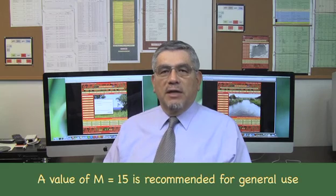In which T sub r is the time of rise of the inflow hydrograph, S sub O is the bottom slope, D sub O is the average flow depth, and G is the gravitational acceleration. The greater the left-hand side of this inequality, the more likely that the flood wave is a diffusion wave. In practice, a value of m equal 15 is recommended for general use.